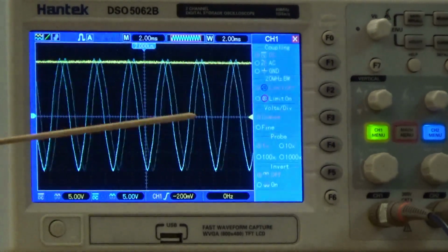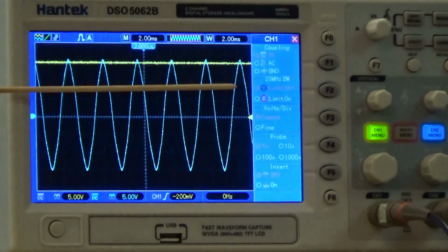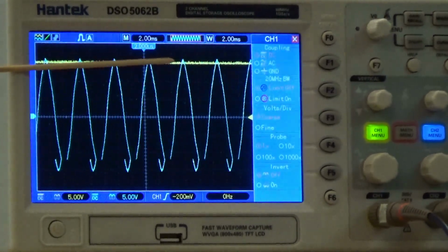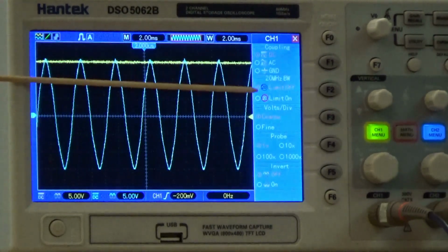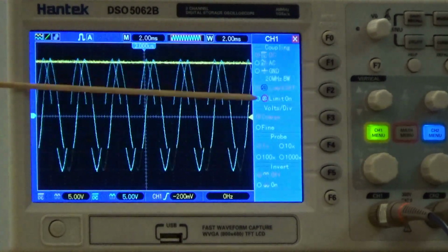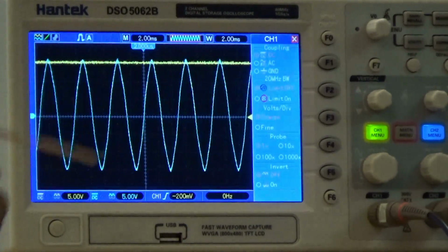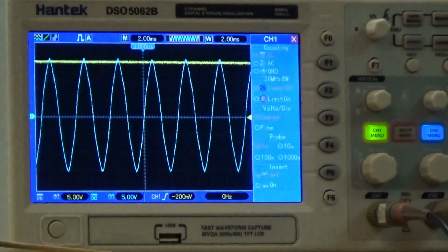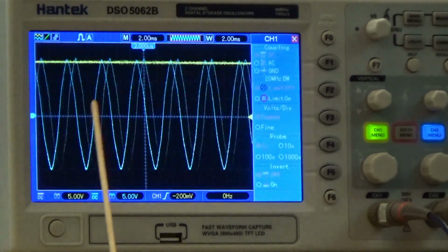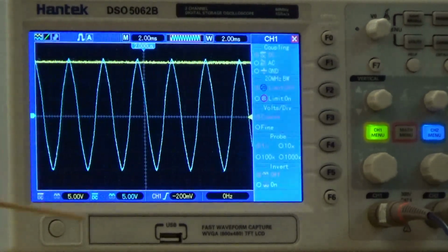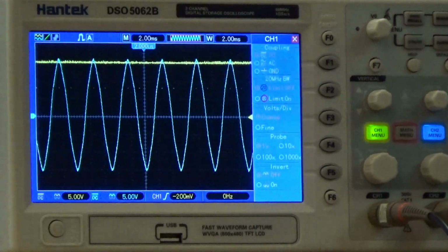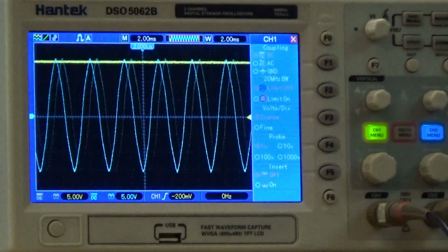And you recall in one of the earlier sessions I said when we rate alternating current, we don't base the voltage on the peak. We base it on a special average. It's about 70% of the zero to peak voltage. The reason the direct current is sitting up there as an average is because we have 3 phases feeding into it. So it's filling in the gaps that a single phase voltage would have.